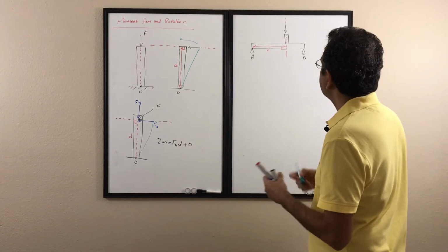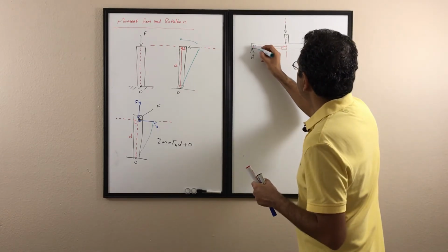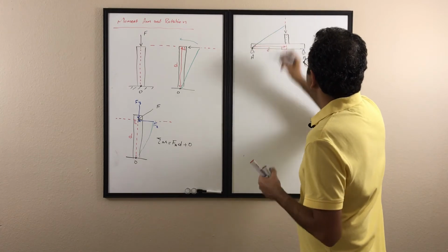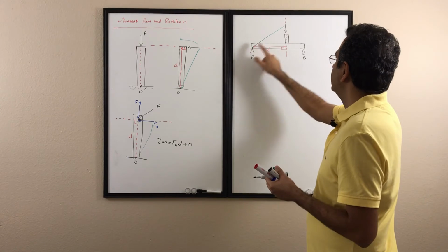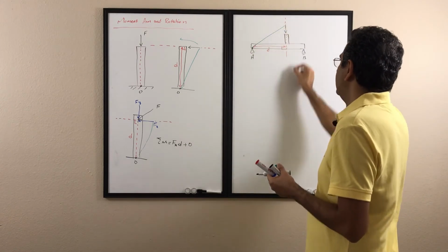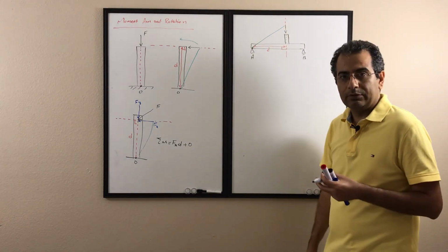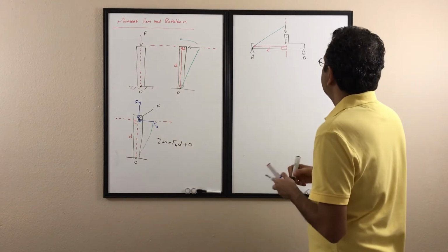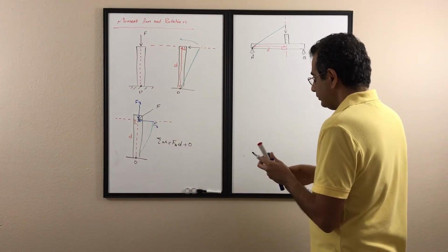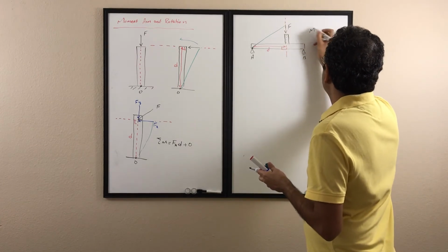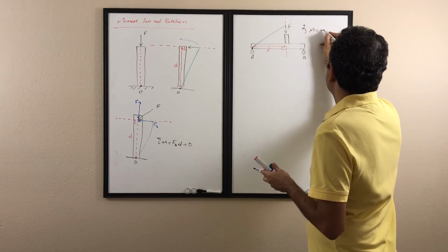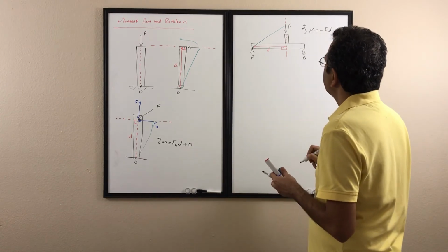And which direction is going to rotate it? Again, assume there is a rope connected from the O to the end of that force, and look at which direction is going to rotate it. It's fixed here. It can move on the other end. So it's going counterclockwise. So the moment created here is, assuming counterclockwise positive, M equals F times D.